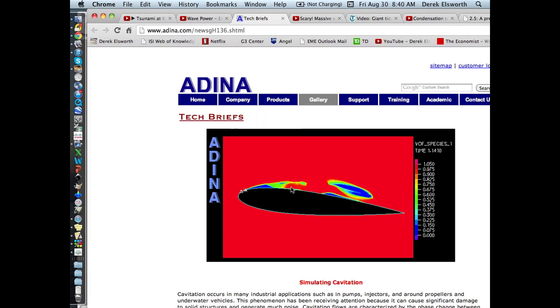As you go across the top of an airfoil, the area on the top is at a lower pressure. And so at that lower pressure, what happens? If you increase the pressure, you compress the gas. If you decrease the pressure, you expand it. You know that when you compress a bicycle pump, it gets hot because you're compressing it. The opposite happens if you expand it, it becomes cooler. So as it expands, it chills. When it chills, it actually condenses the vapor that's in there out of the system. So the pressure change is driving a temperature change, and that temperature change is allowing the vapor to be condensed in that particular case.